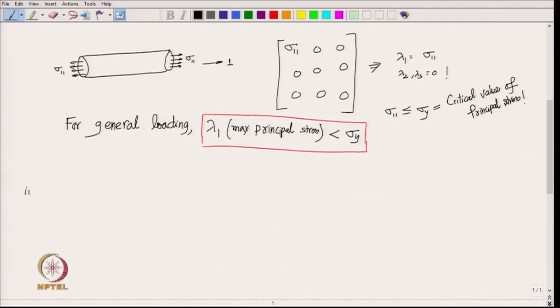So, that means the maximum principal stress theory is not working there, is it not. Therefore, the mechanicians went ahead for another theory of failure. The second one is the max shear stress theory.